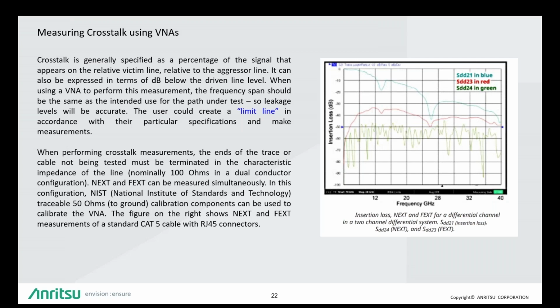So what you see on the picture on the right is you could measure the NEXT as well as the FEXT for a differential channel in a two-channel differential system. So you have three traces over there. You're measuring the insertion loss as well as the NEXT and FEXT crosstalks. Very useful.